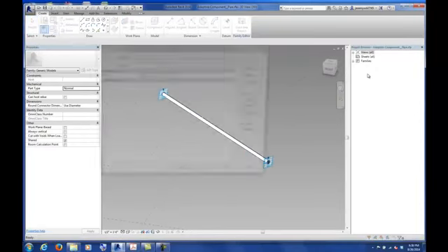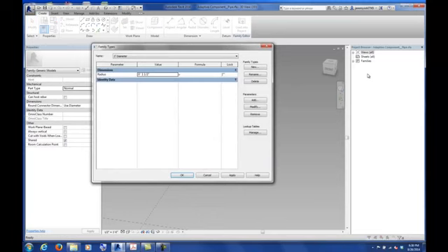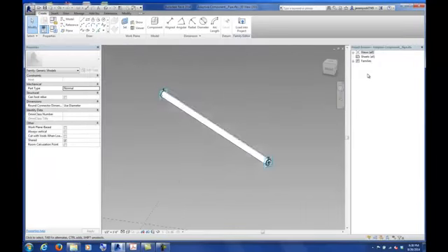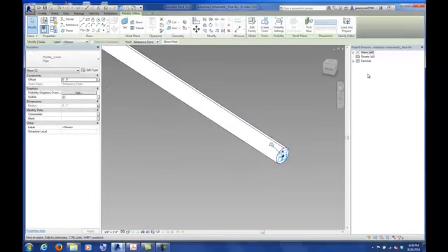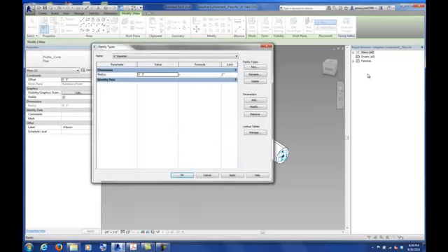Now if you remember, we have this radius that was tied to like a 3-inch diameter or a 6-inch diameter, and that was also tied to those profiles at the end. If I tab over the end profile, I'm making that radius equal to that profile, something that I've already programmed within this family dialog box.